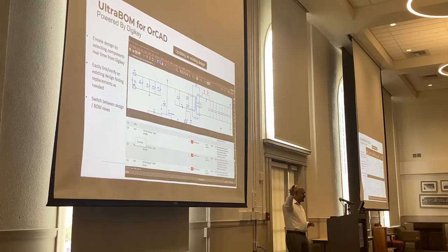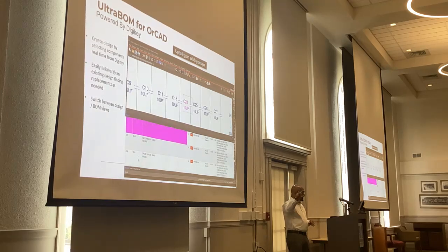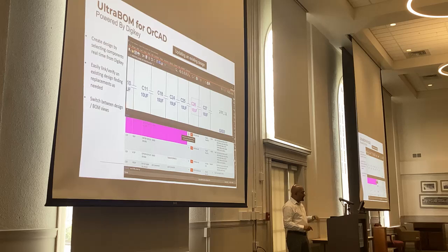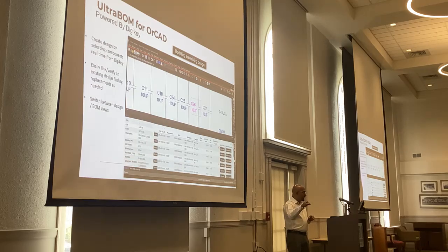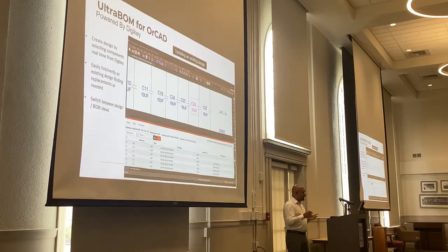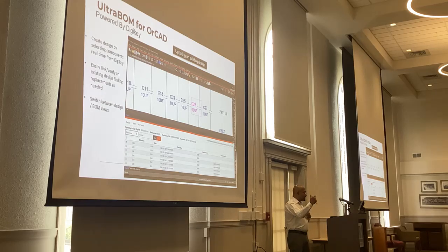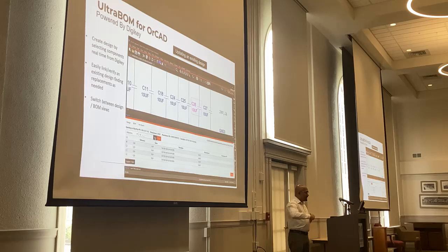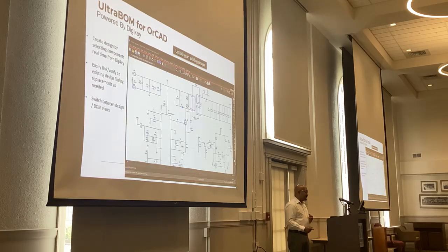So what it does is, as soon as you open up a design, it reads all the design data, links it to DigiKey, and displays that tab with information. So you can cross-probe between that view and the component on the design. And if a part is not available on DigiKey's website or DigiKey's catalog, it will recommend alternate parts. And typically for capacitors or resistors, for example, you don't want to do it one at a time. So you can filter for certain capacitors based on part reference or value, and just update all those parts against DigiKey so it gets assigned a manufacturer part.